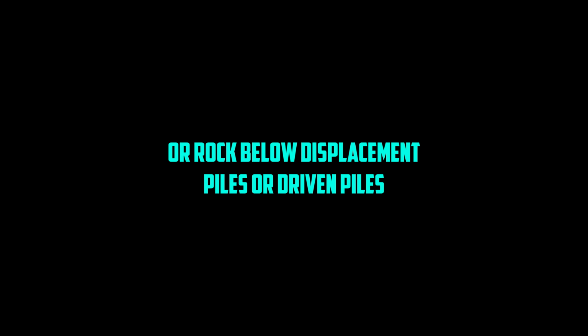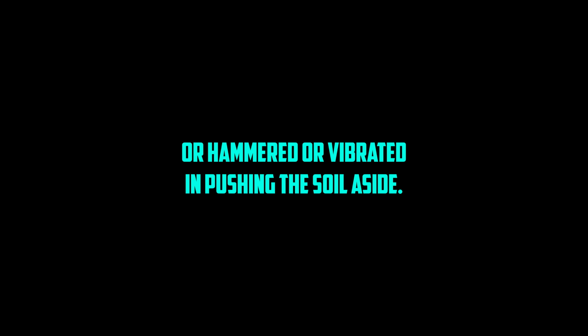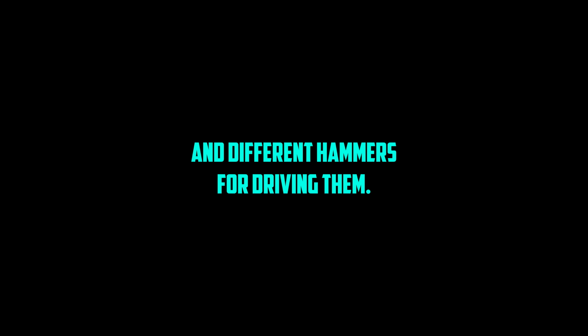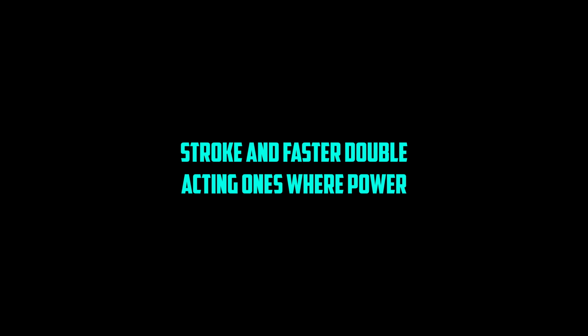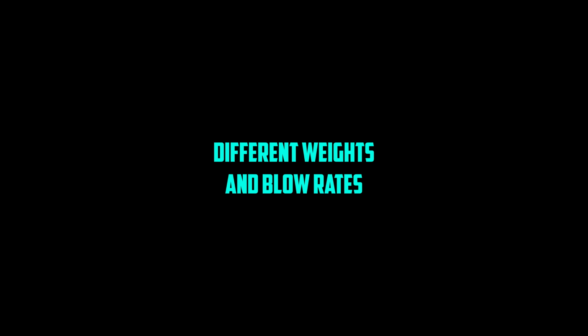Displacement piles or driven piles are hammered or vibrated in, pushing the soil aside. They're driven until they hit a certain resistance called the set. And different hammers for driving them. Yeah, simple drop hammers, single-acting steam or air hammers where gravity does the downstroke, and faster double-acting ones where power drives it both up and down. Different weights and blow rates for different pile types and ground conditions.